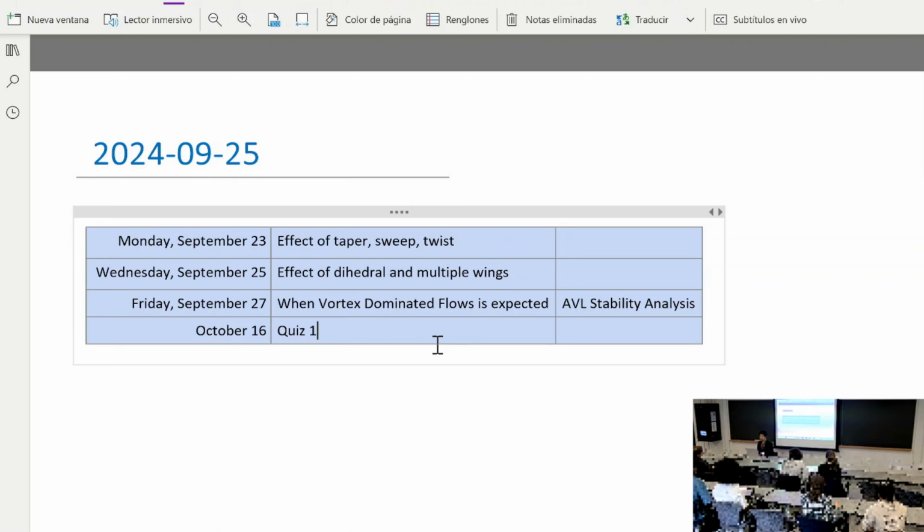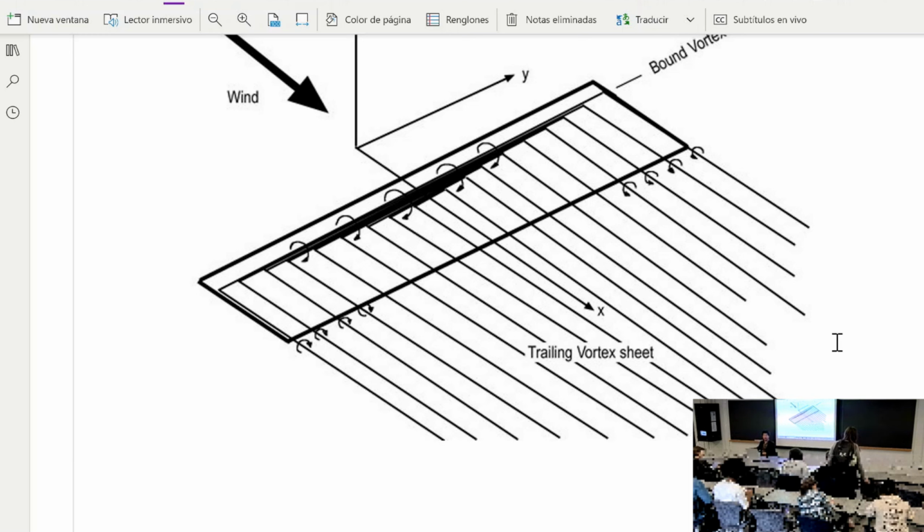Therefore you can compute how much kinetic energy is in the vortices, and from that how much energy per second the airplane has to dump into its wake to sustain it.